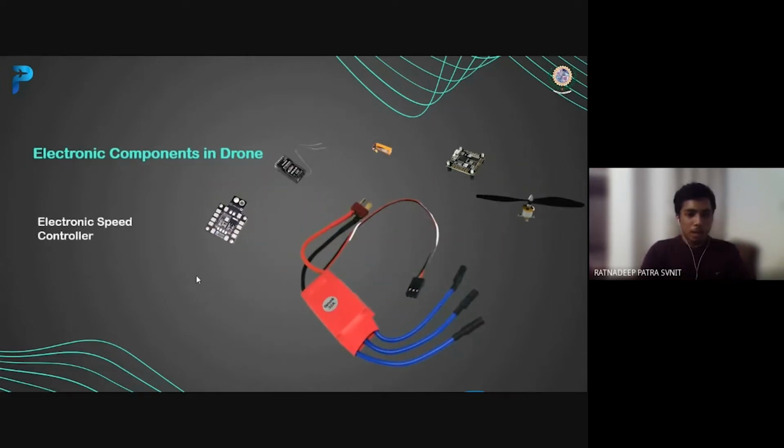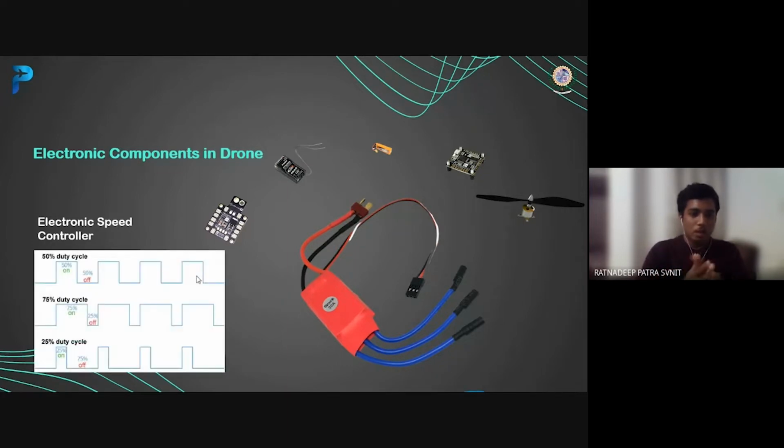Next, we have the ESC, electronic speed controller. The electronic speed controller is basically responsible for controlling the RPM of a BLDC motor. It sends a PWM signal, pulse width modulation signal, and these PWM signals are just rectangular signals in which the percentage of the time when the signal is high in one time period can be varied, as seen in this picture. This percentage of the time for which the signal is high is what we call duty cycle.